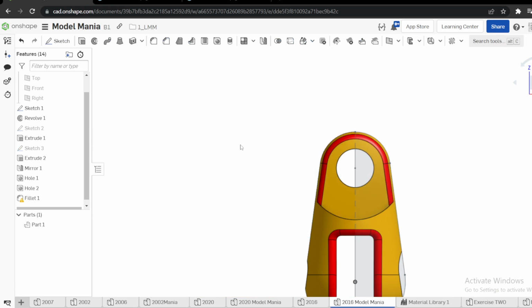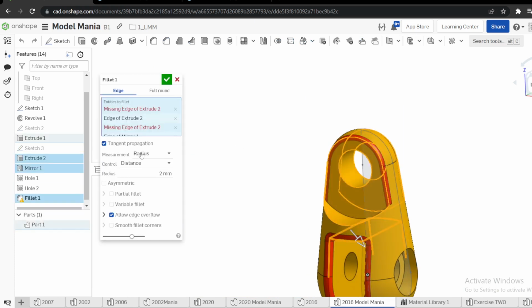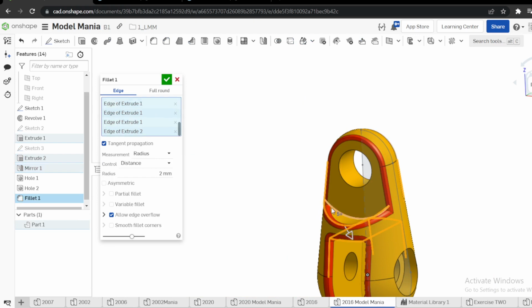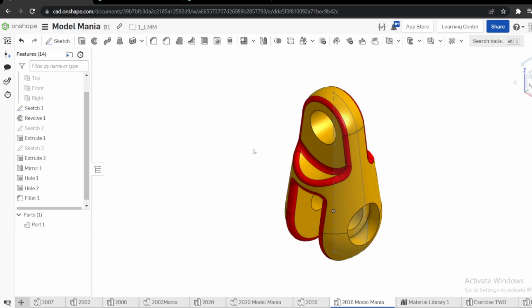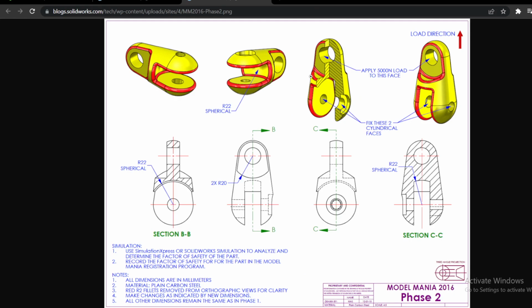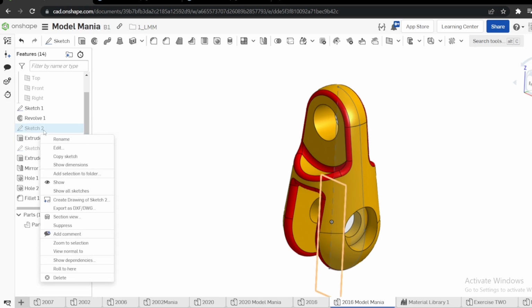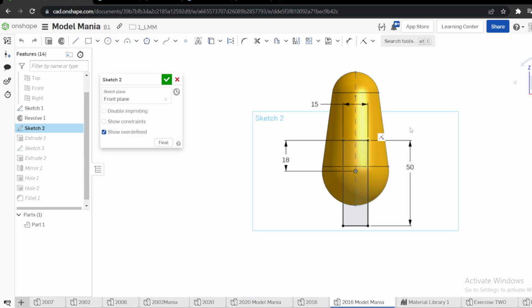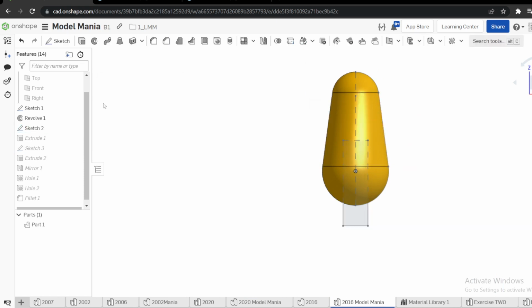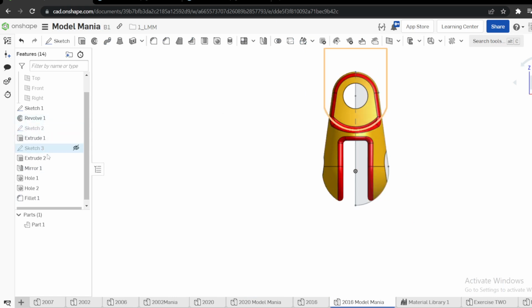That's fine. Therefore, you have to rebuild your sketch because now a few edges are missing. This and this, this and this. Okay, we have done that. You can see this type of cutout. Then next one we need to do some revolve here. I'll show you. You can either put a curve and revolve cut, or you can use another method. Let me go back here and use another method here.